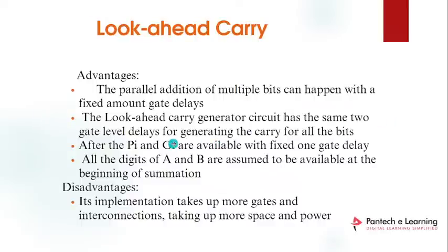They are doing the parallel addition. I already said, they are doing the parallel addition of multiple bits with a fixed amount of delay. Carry look ahead adder generates a circuit with the same 2 gate level delays for generating the carry for all the bits.